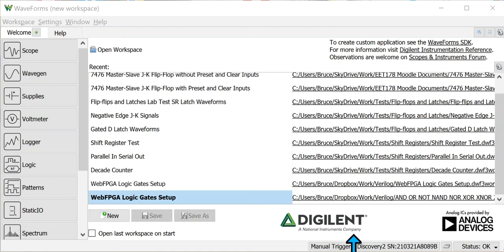In the troubleshooting environment, signal generators and pattern generators aren't used too often. The other advantage of a pattern generator is it has many channels. In our case, up to 16 channels can be used to generate patterns at one time, and you could not do that with a signal generator in the analog world. So let's jump in and try and explain this a little bit.